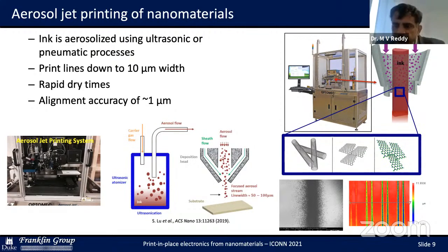Okay, so in principle, viscosity is the main issue for your case. Viscosity you take into consideration. Viscosity is a big one to take into consideration. And aerosol jet, for an additive printing approach, compared to almost any other printing approach, gives you the most range of viscosity that you can utilize in an ink. Okay. Because for my case, if you use too much polymer, based on viscosity, it's not really good; I'm diluting my battery material. Anyway, it's a very useful technique.